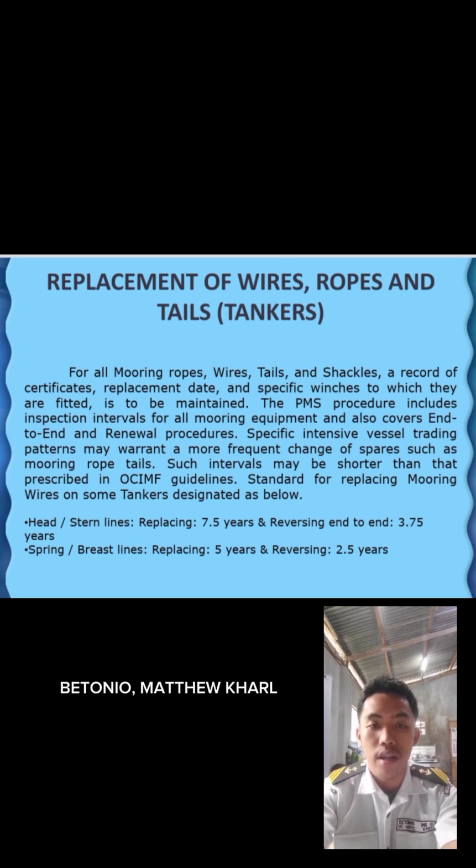OCIMF guidelines. Standard for replacing mooring wires on some tankers is designated as below. Head or stern lines: replacing at 7.5 years and reversing end-to-end at 3.75 years. Spring or breast lines: replacing at 5 years and reversing at 2.5 years.